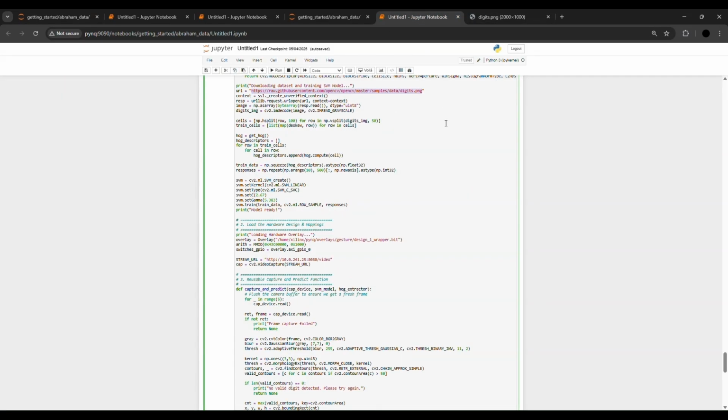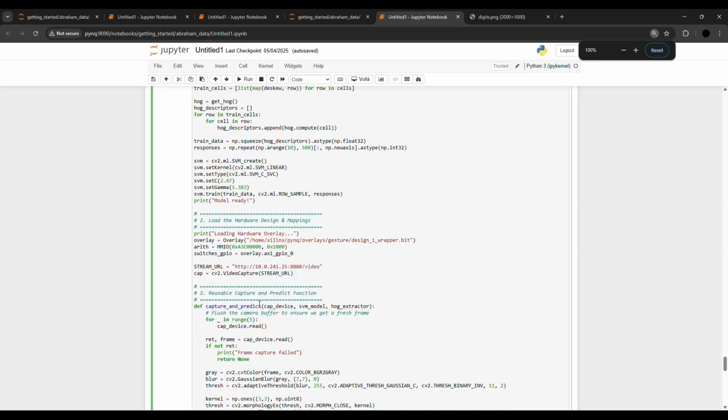Initially I tried with a video camera, but unfortunately it was a good quality camera, so the PYNQ board couldn't handle it. We had to install a few drivers, which was very hard to install on the PYNQ, so we had to create an IP stream from a camera in the phone. This is the stream URL. You can download an app called IP Web Stream from the Play Store, and then you can share your web stream.